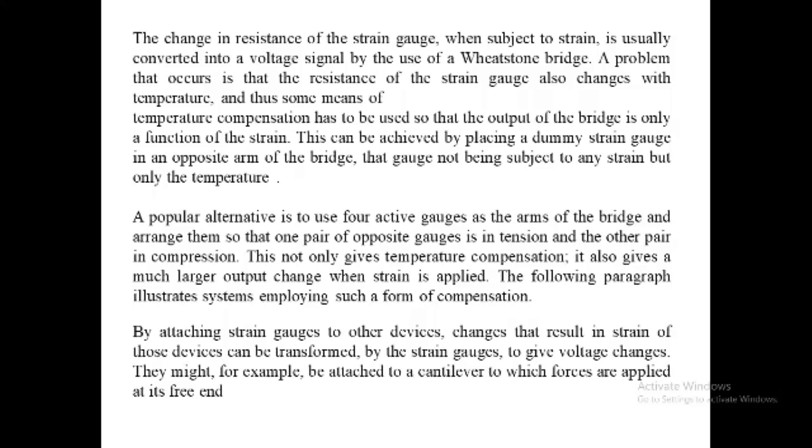By measuring the change in the resistance of an object, the amount of induced stress can be calculated. The change in the resistance normally has a very small value, and to sense that small change, the strain gauge has a long thin metal strip arranged in a zigzag pattern on a non-conducting material called a carrier, so that it can magnify the small amount of stress in the group of parallel lines and it can be measured with high accuracy.